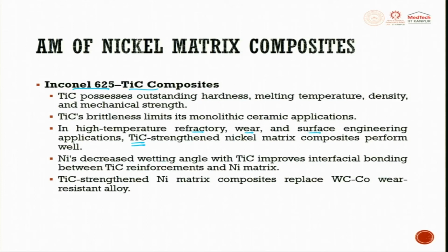Ni decreases the wetting angle with TiC, which means it can easily spread over TiC and improves interfacial bonding between the TiC reinforcement and the Ni matrix.